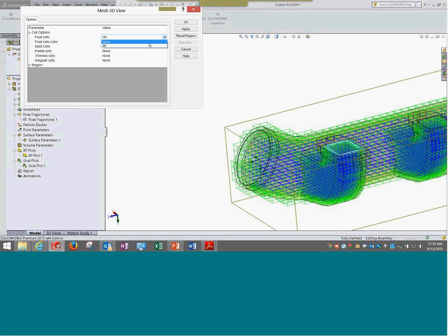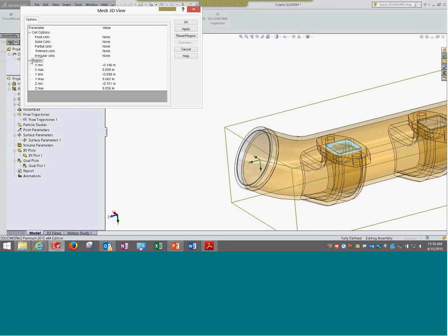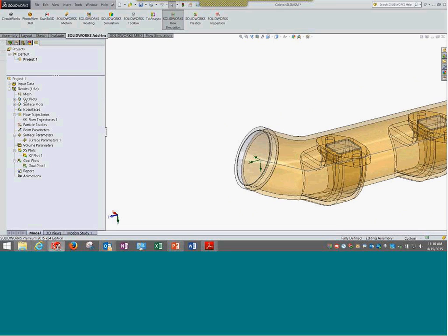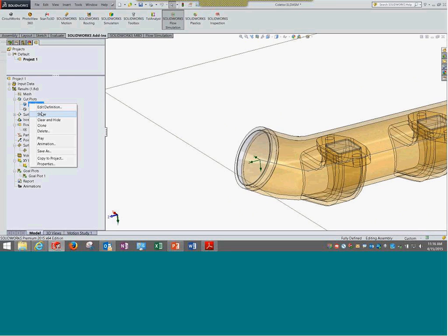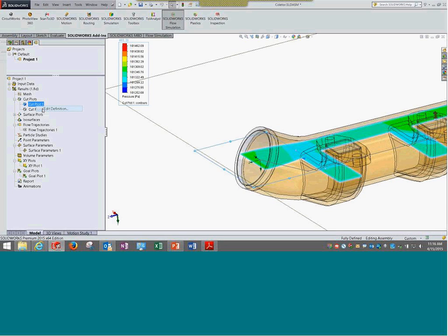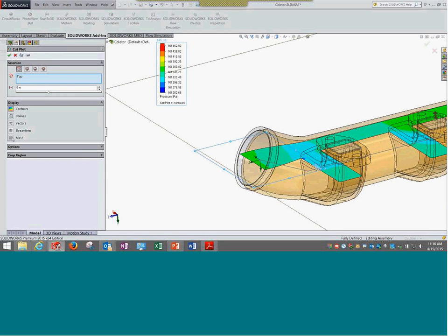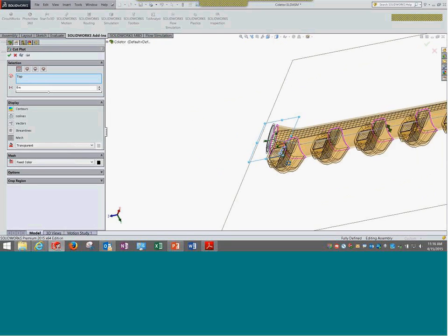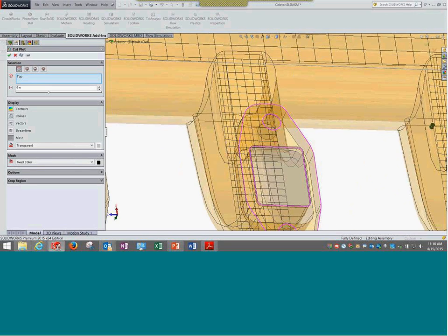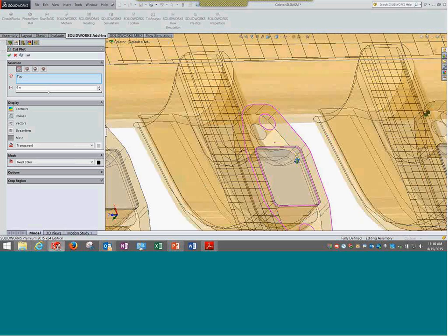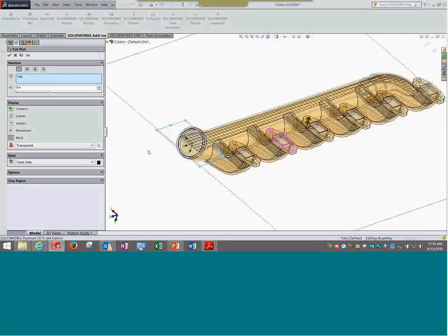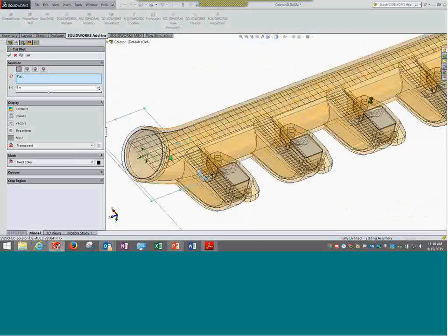But these are a few options which can be used to visualize those in 3D. Frankly, it does not make much sense because it is difficult to understand what's happening around, but the option is present. More of these 2D plots with mesh can actually show you those details. Yeah, transparent. This is far more relevant and can give you a good idea of how the mesh is created. A plot or a cut plot with mesh only can show you far more details, and the results that can come from this one are more interpretable than the other one.